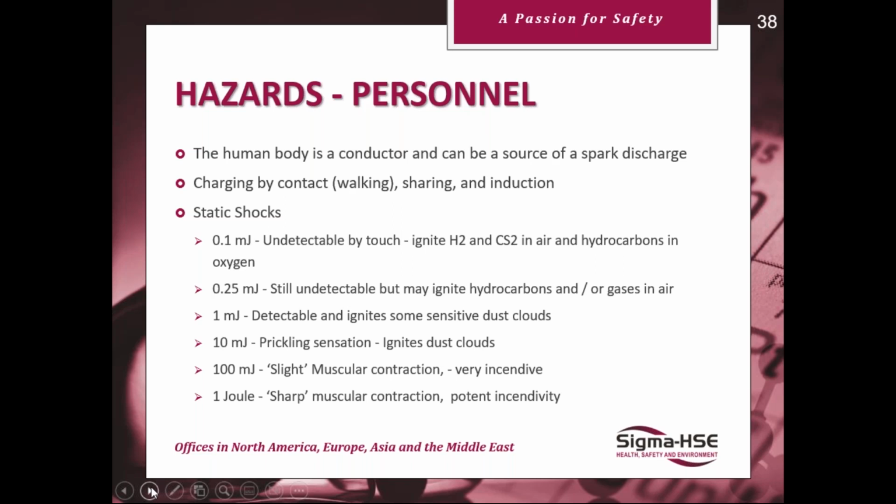If you want to know certain levels: 0.1 millijoules is undetectable by touch, yet it still ignites hydrogen and carbon disulfide in air and some hydrocarbons in oxygen. 0.25 millijoules is basically undetectable by us, but may ignite hydrocarbons and gases in air. One millijoule is detectable, like a feather brushing against your fingers, and can ignite some sensitive dust clouds.